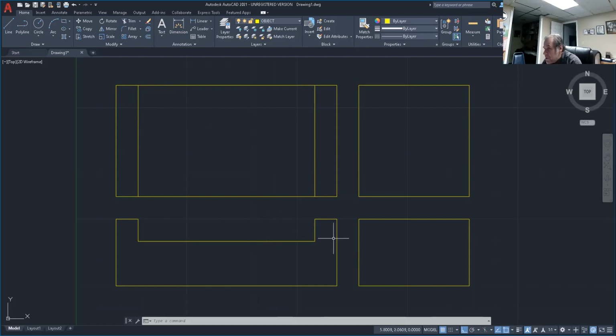Now we got to finish this in our right side view. So I'm going to draw me a line now from here, coming over to here. Now, we talked about the trim command, didn't we? So trim is TR, and I can trim this off and that off there. But how do I get this line over to here? I would probably say, I want to extend that line. Do not draw another line. Keep one line with no line segments.